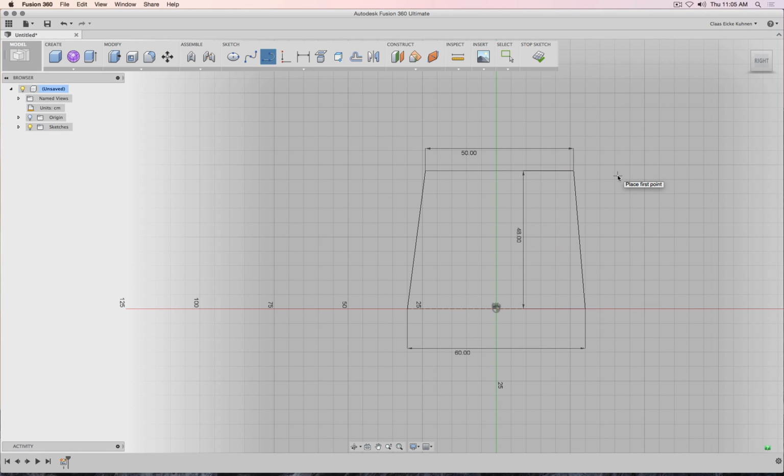Okay. Out of curiosity, what's the length? 48, good. We can actually do interesting things like this. I select these 2 points and give me a dimension. So you see, maybe I could say, well, in the back I would like to have 6 centimeters. And what about these 2 points? Give me a dimension, 4 centimeters.